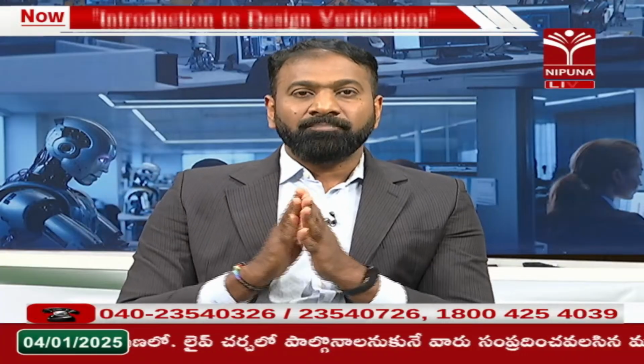Now, how can I say that the rest of the functionality is matching? Formal verification can help you match or map the majority of the functionalities, so that you can say, okay, this new design which has the bug fixes is fully formally verified, and I can make this design the golden design for the subsequent steps. In that way, formal verification helps you with a lot of equivalence checking, property verification, and data path verification as well.